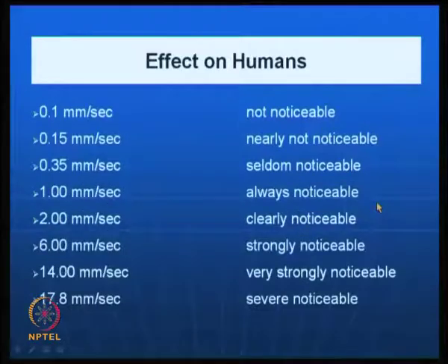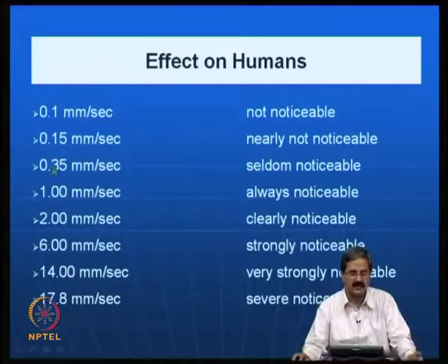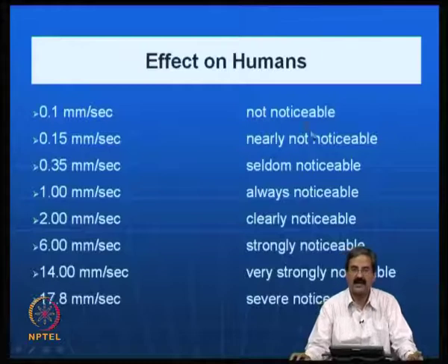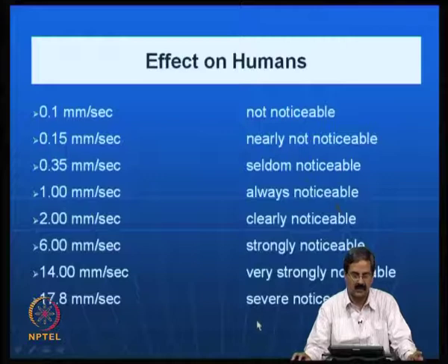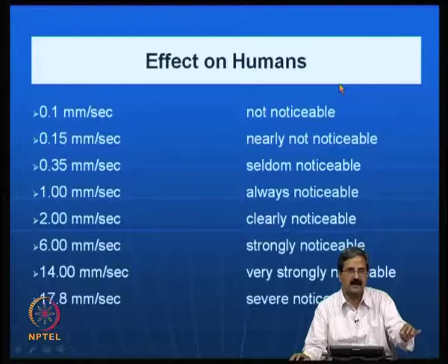In fact, there is also the effect of these vibrations on humans; you do not want to tolerate these vibrations. Even when the earthquake came, nobody must have slept in Delhi or somewhere, right. So, you see that velocities as small as 0.1 mm per second are not noticeable, and you have a scale here, from not noticeable to highly noticeable. You have a classification here. One should really measure this peak particle velocity.